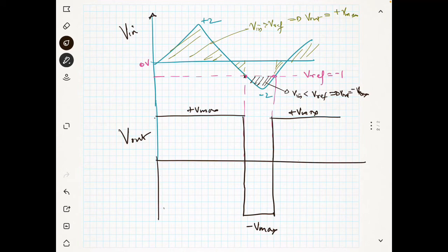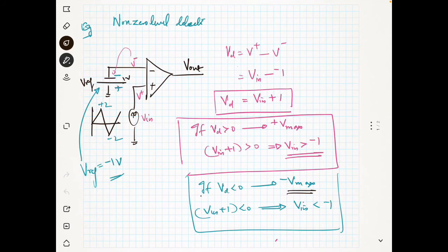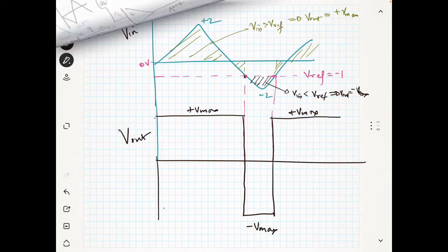Now you have to draw like this for the exam. Whatever I have told now, I am using a battery here. This is a battery. Instead of a battery, I can use a voltage divider, because if you want to set the reference voltage as 1.9, it is not possible by using a battery. Sometimes it will not be available.